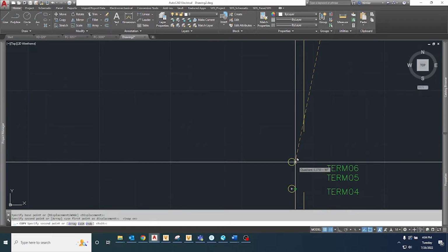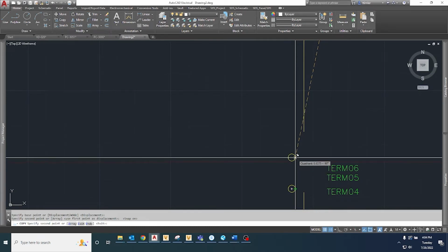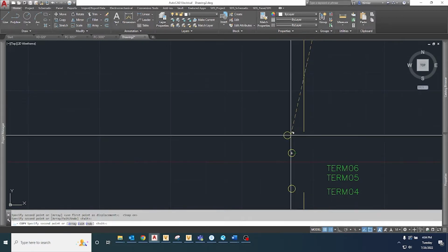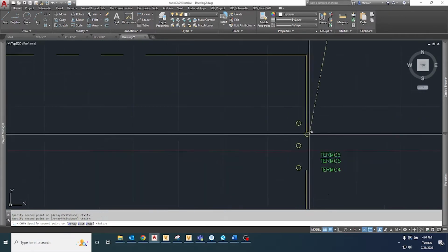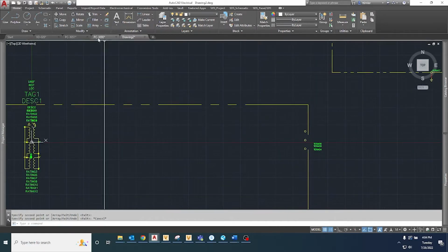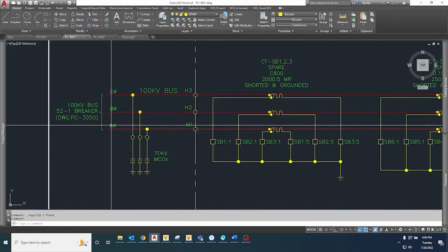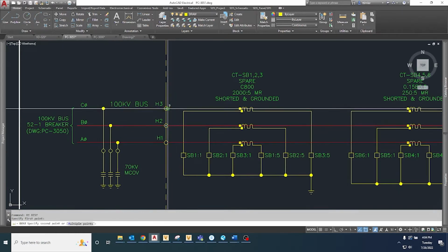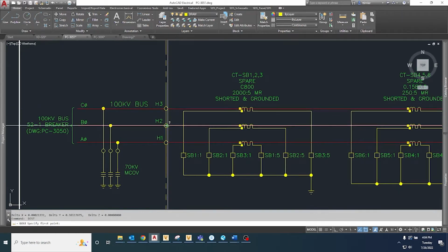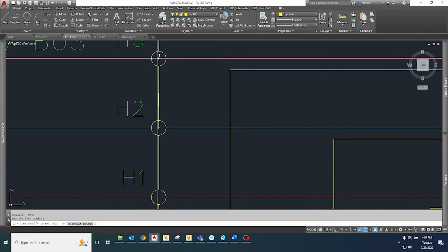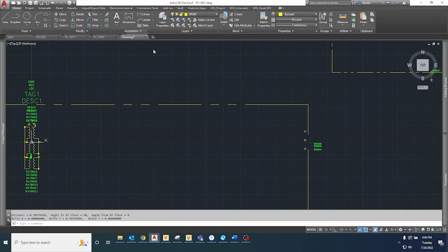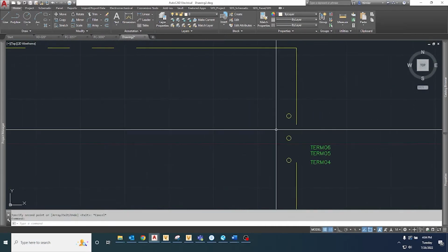I'm going to position these terminals with a 1/2-inch spacing. I'm almost positive the original drawing doesn't have this spacing. If I go back and do a distance check just to verify, I can really see that it's not. So we've standardized on a 1/2-inch horizontal bus spacing, so that's how I'm going to space these bushing terminals out.